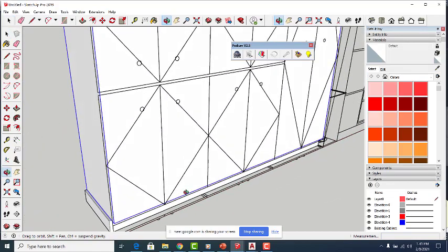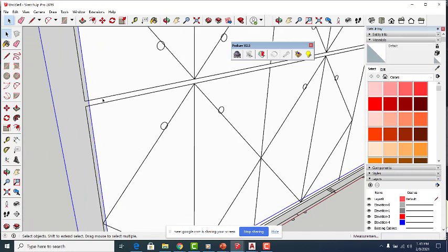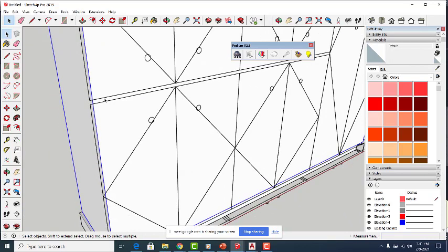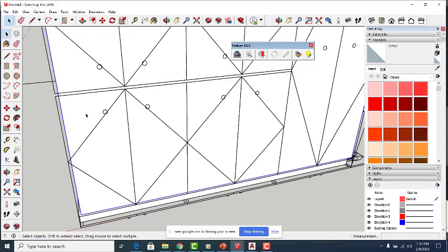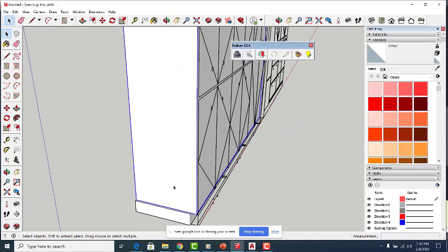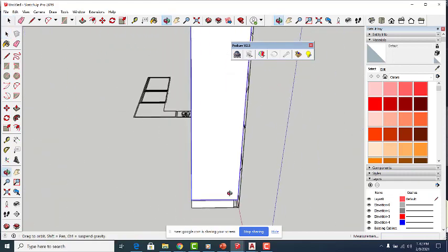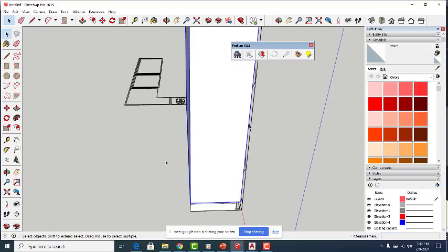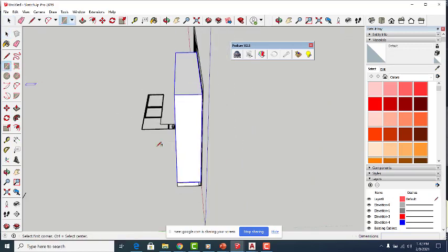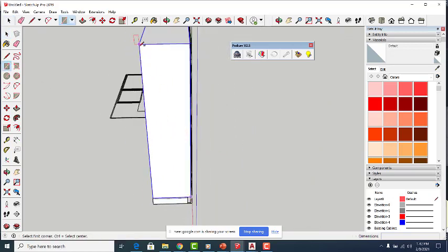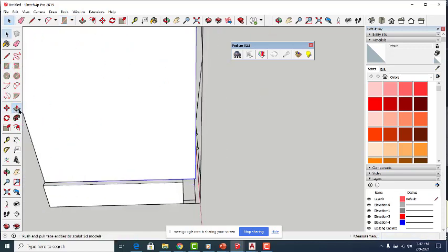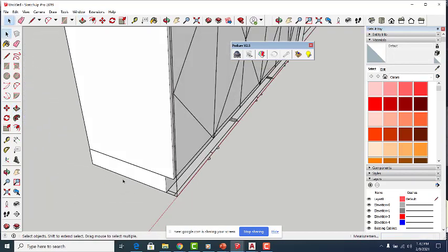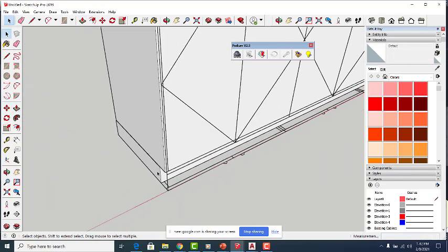So now what I see here, I see a gap here. I don't know, do you want a gap between your doors, Carla? Okay. So then I just follow the same steps. First of all, maybe I add this panel because as we can see, we have a panel here. It would cover this part. So what I can do is draw a rectangle from here to here. Then I use the push-pull tool and I match it here. So now I have the side panel for this one.